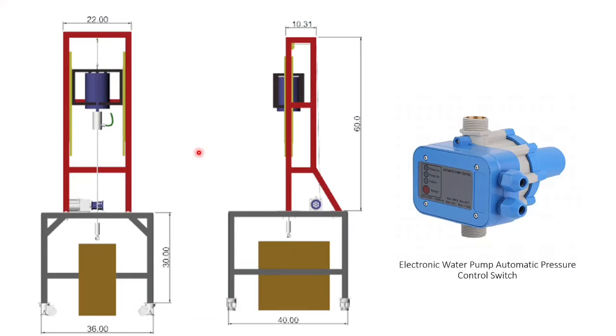For this section, we'll be discussing our fluid circulation system. Our fluid circulation system typically begins at the surface from the mud pump. Our mud pump for this system is sized to overcome all the pressure losses in the system and have an additional margin of 100 psi. Fluid enters the drill string via the hose connected to the swivel.